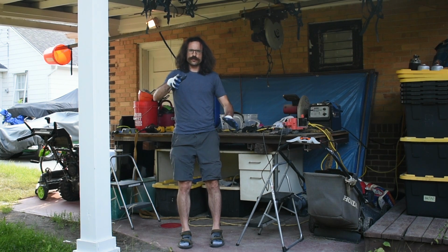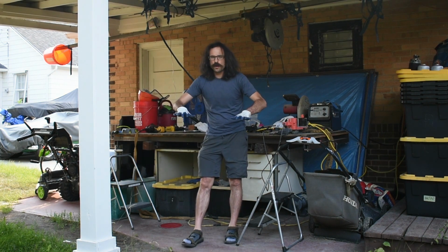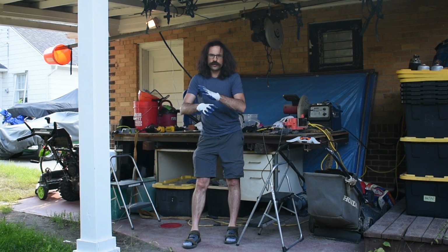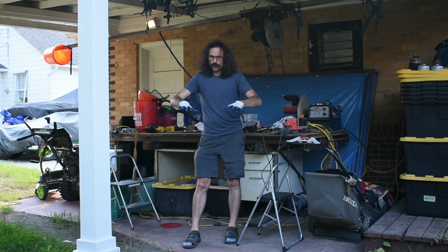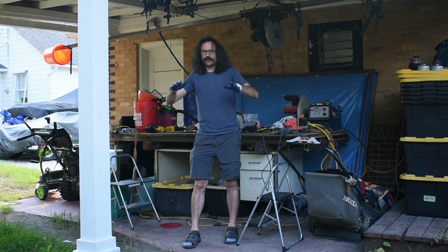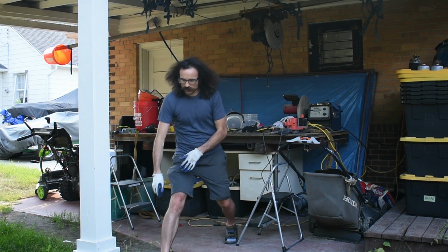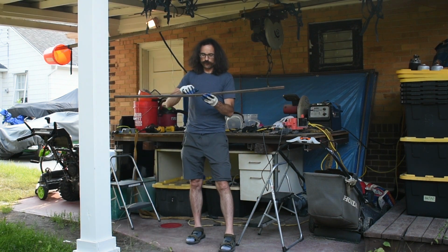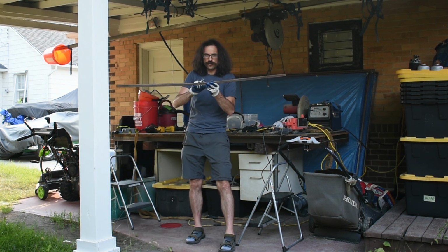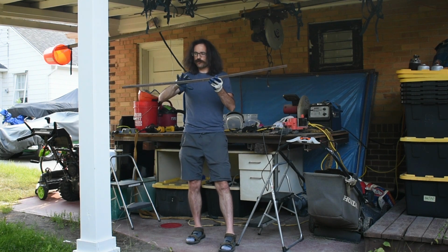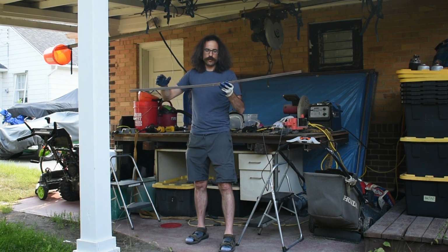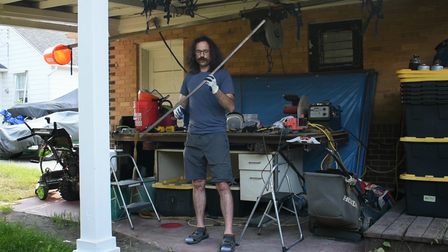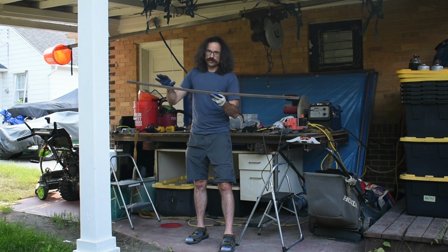Thanks for joining me. Now, that was a huge amount of deflection, but we can't use the deflection equation because it wasn't linearly elastic. This piece didn't go back to the original shape. It's permanently bent. In the elastic range, you can put a force in there, measure the deflection, and then back off, and every molecule is going to go back to the original shape. Obviously, we didn't see that, so if we do get deformation, that equation doesn't apply.